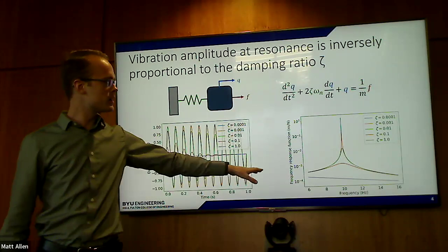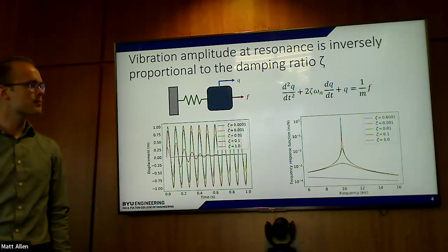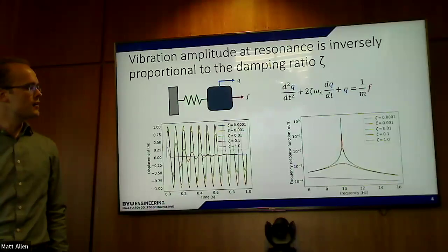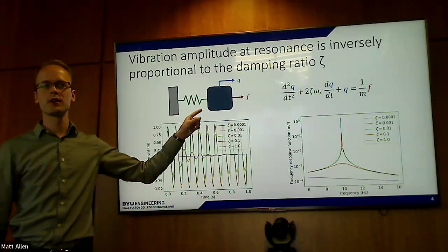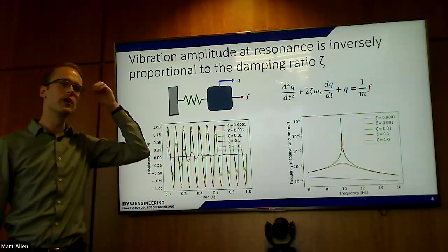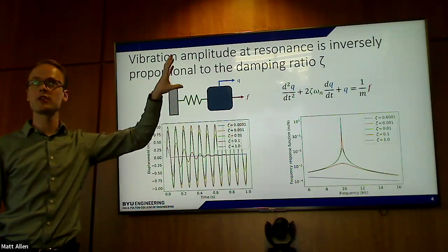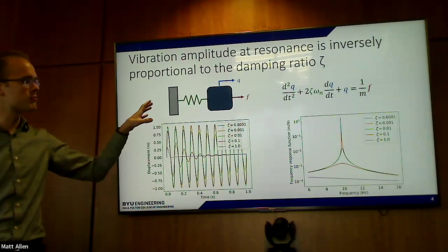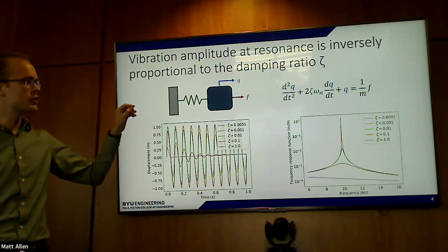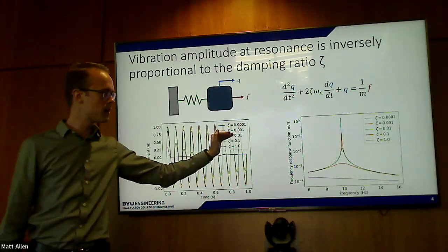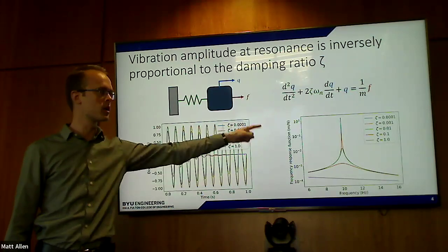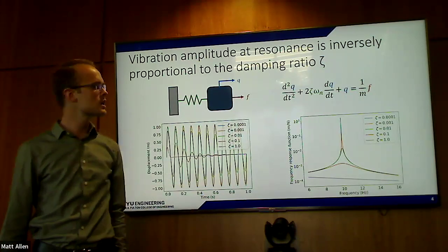And what we're showing on the right is a frequency response function. And this is something that we look at a lot in vibrations. And the way to interpret this is if my input force were sinusoidal, say you had a motor with an off-centered load that's spinning at a given frequency, what would be the ratio of the response amplitude to the input force? And that's what we're plotting on this axis in log scale.